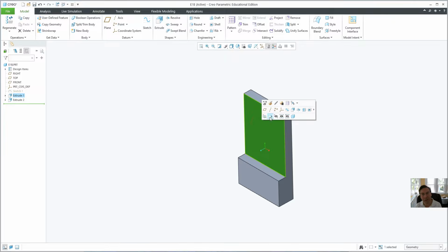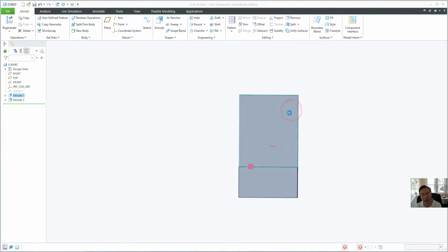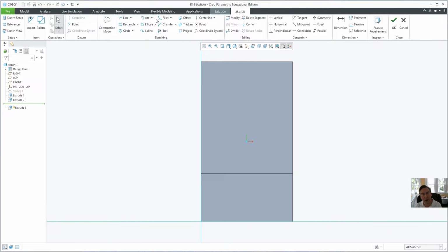Click on this surface and let's go to extrude again. Now go to circle. Notice there's a couple different types of circles there. Just center and point circle is fine. And hover this upper left quadrant, click, and draw out a circle that looks kind of like mine. Take a minute and then click again. And now middle wheel click, and it brings up the dimensions. So this is a good dimension. Let's drag that out. That's the diameter. Double click on it. Notice it said it was weak. Go ahead and type in 0.75.